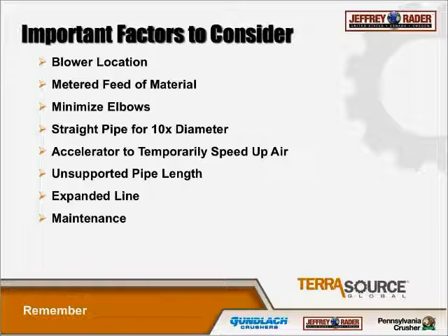Maintenance is very important. Extend the service life. If you have any kind of leak or hole, you want to make sure that you fix it properly. Spot patching is just not going to work because it's really just going to make the system get worse and worse. And if you want that system to run at full capacity, full efficiency, you want to inspect and make sure that everything is not worn. A lot of mills will rotate the pipes even to extend the wear life of their pneumatic system.